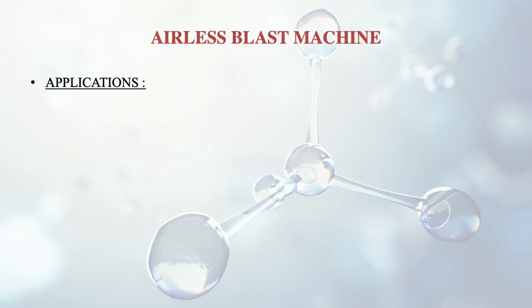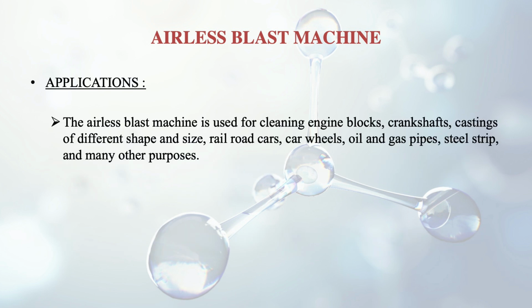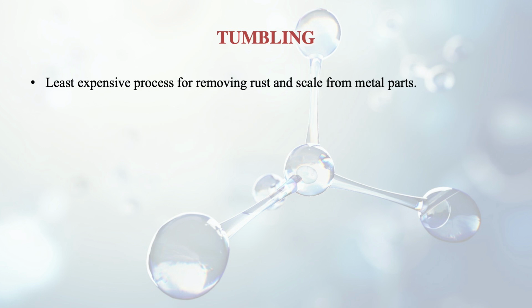And what are the applications of these? The airless blast machine is used for cleaning engine blocks, crankshafts, castings of different sizes and shapes, railroad cars, car wheels, oil and gas pipes, steel structures. So it has got many applications because it gives us a very good or excellent surface finish. Next process in mechanical type is the tumbling process, and this one is the least expensive process for removal of rust and scale from metal parts.